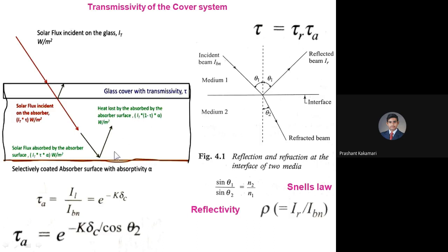Why? Because it is coming from the absorber plate and it is having some losses. So we take 100 minus that loss, how much is retained in the reflection, and absorptivity means after absorbing by the plate, how much is available, that we are going to multiply. So finally, how much is reflected will be very small compared to the total radiation coming from the sun.